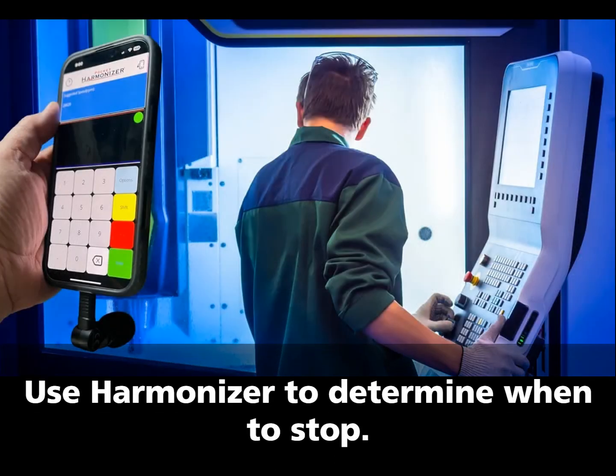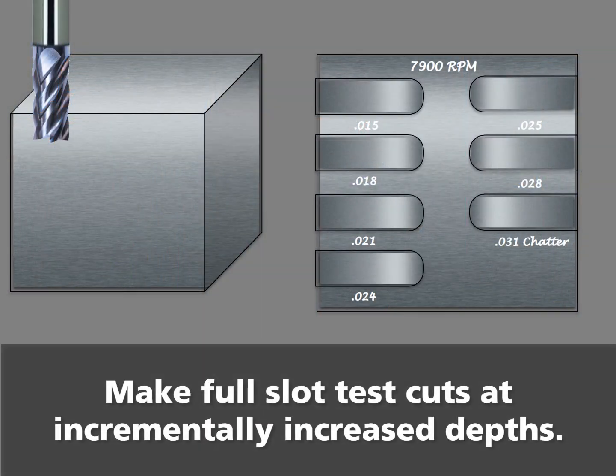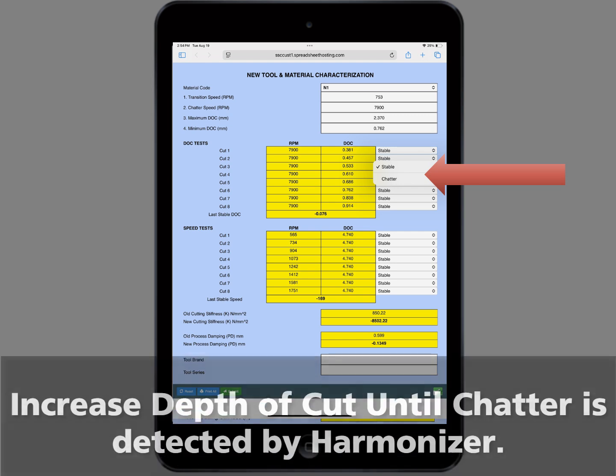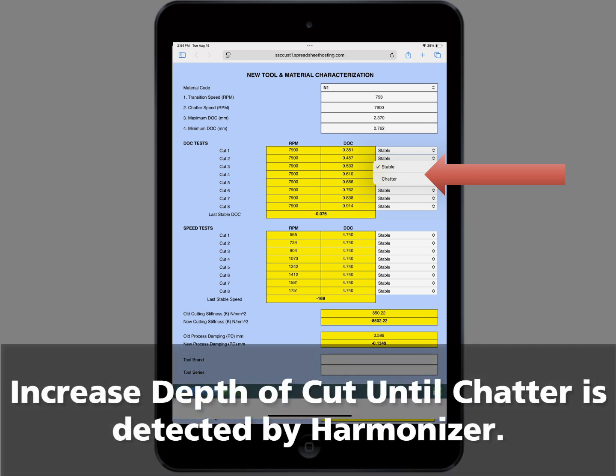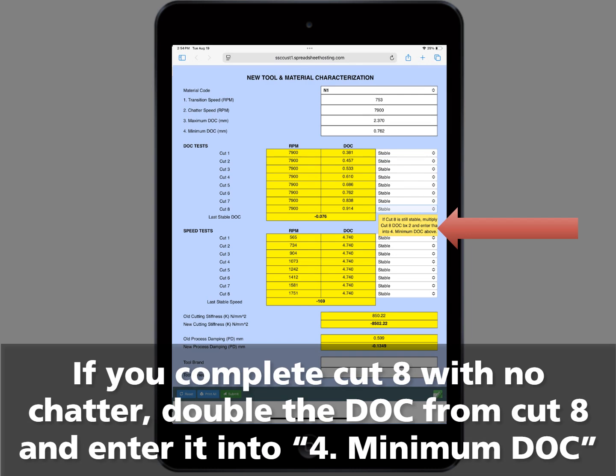You will use the Harmonizer to record each pass and to determine when to stop as soon as chatter is detected. Make full slot test cuts, at incrementally increased depths, as shown on the calculator. Conduct the test passes at the same RPM shown on the calculator, and at the calculated progressively deeper cuts. When chatter is detected by Harmonizer, choose chatter from the drop-down menu next to that depth of cut. If you complete cut 8 with no chatter, double the DOC from cut 8 and enter it into number 4,